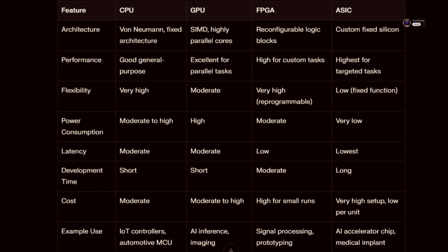And finally, I'm designing a main processor for the next iPhone. I know I'm going to make 100 million of them. It needs to be incredibly powerful, sip battery power, and fit in a tiny space. The functions are well-defined: run the OS, handle the camera, accelerate AI. That's the mass market high efficiency play. You bite the NRE bullet and go for the custom designed optimized ASIC. You got it. Best performance per watt, lowest cost at extreme volume, smallest size, that's the ASIC.